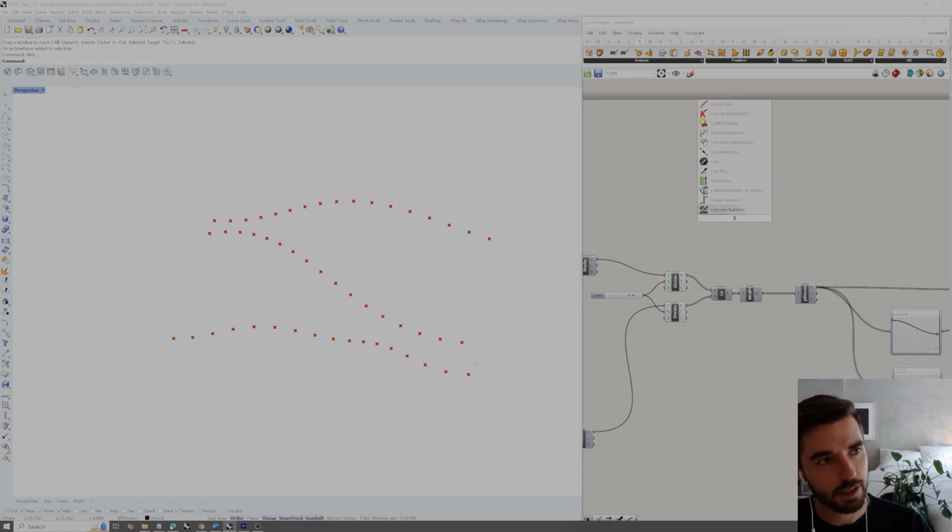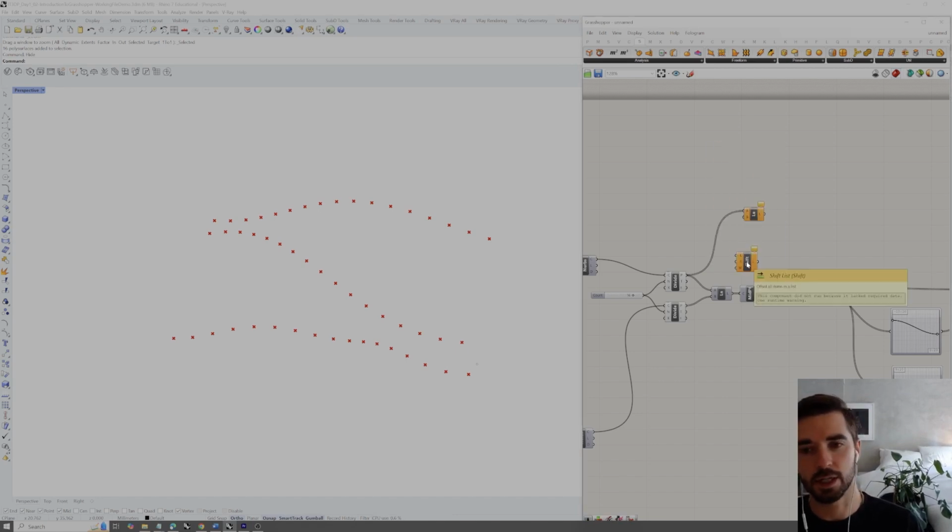So what this looks like is we have to first make a line component again. We can draw a connection between these points, and those are going to be all of the first points in this line. And then we want to connect each of those points to the next point. So Grasshopper actually has a component called shift list, which is going to take that list and just shift it up 1, meaning that the first item in that list will become the second item in the original list. So everything just shifts. So to use this, we just have to plug in our list.